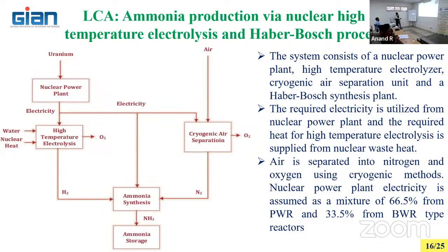Then you are going to provide some kind of energy to separate oxygen and nitrogen by using a permeable membrane. So inputs are energy and air, outputs are oxygen and nitrogen. Along with that, some amount of heat also will come out because you are going to send high pressurized air. So other forms of energy also will come out. That also you take into account. Okay.